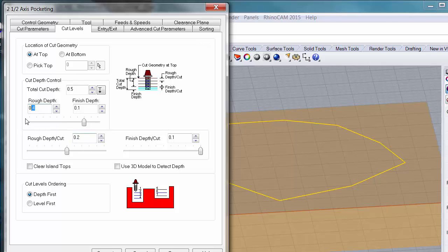If these numbers don't equally divide out, it's going to make a last roughing pass at kind of the leftover amount. So I tend to make these kind of match. Finishing depth gives me a second zone, and by default it's going to come in here at the full depth of 100 thousandths, and I could select this at, say, 50 thousandths, and that would force it to do 2 finishing passes, or I could leave it with a 1/4" cutter.